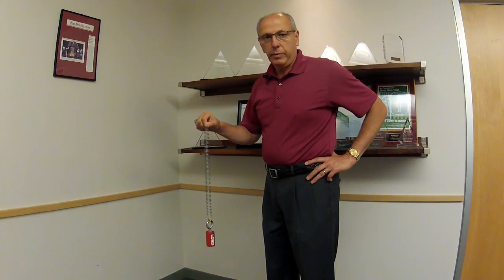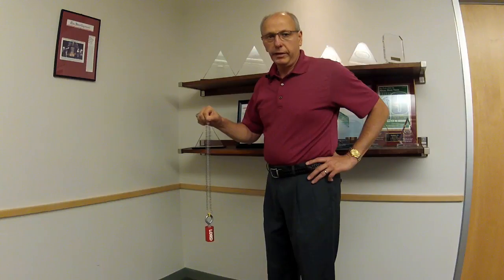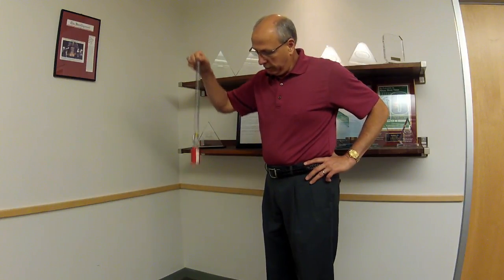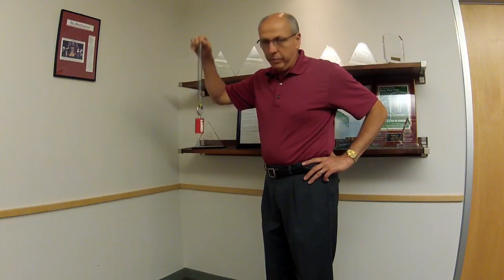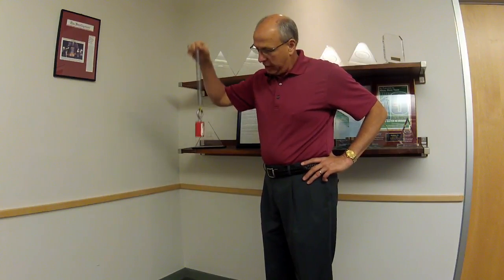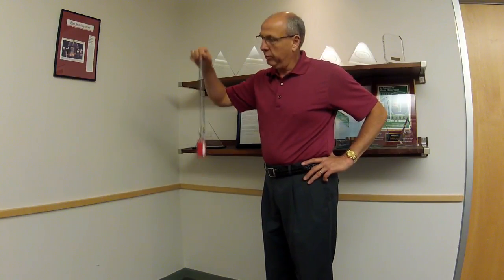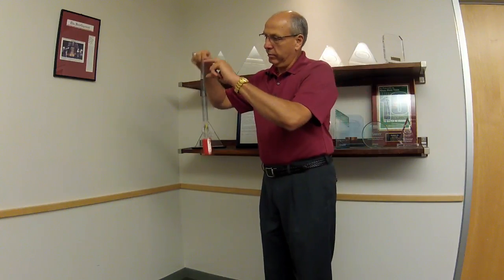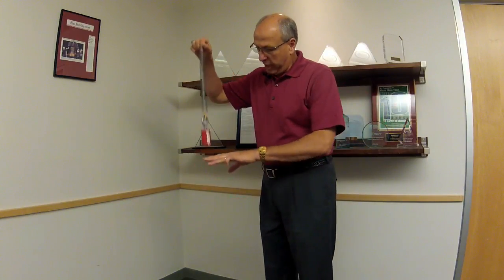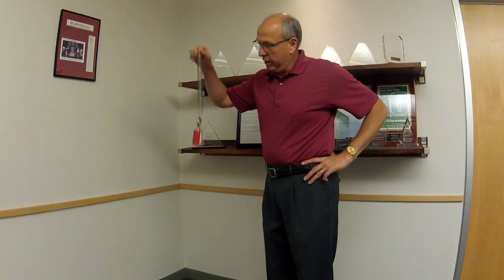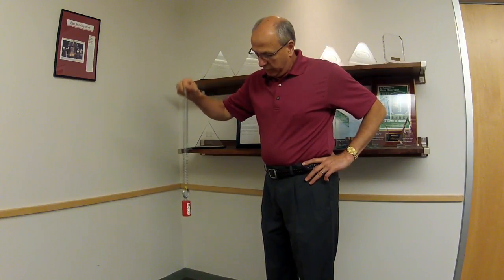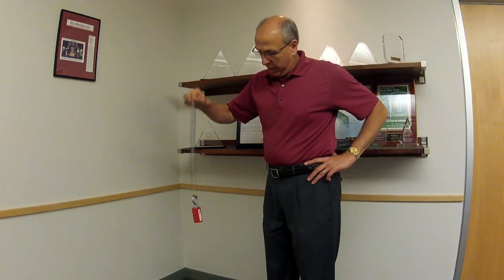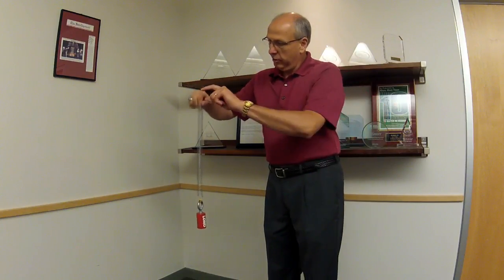The next part of the curve is transmissibility at resonance. You can see a little bit of input in my hand, and the spring is exciting the mass quite a bit. So it's amplifying the input that I have here; the mass is getting amplified. If the input increases, you can see that the mass is isolated from the input here.